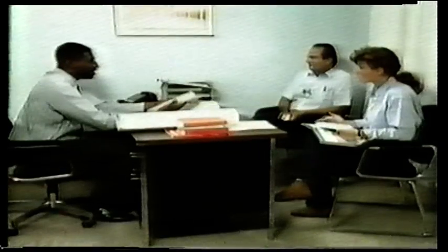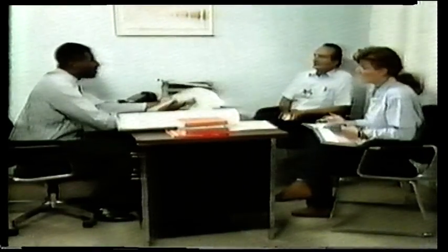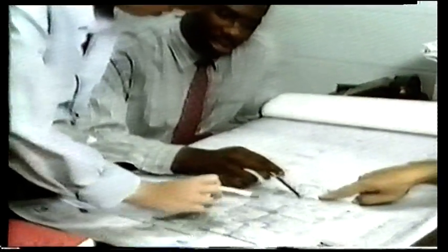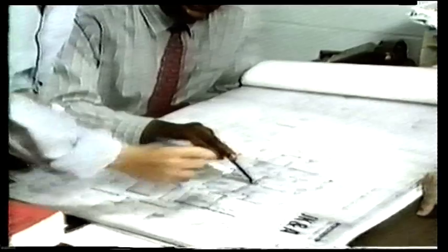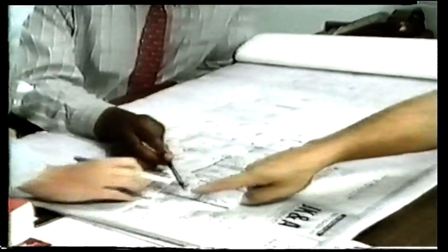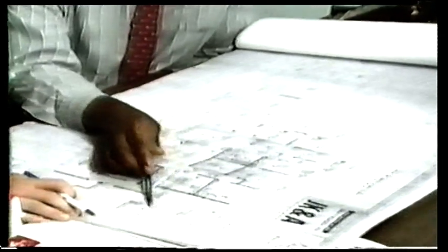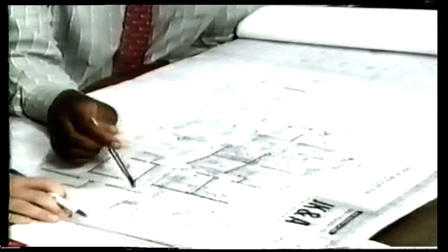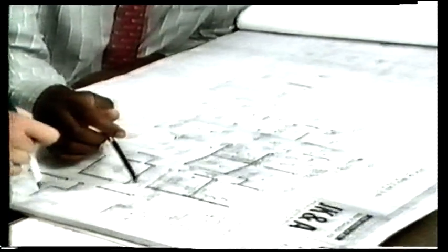The survey team should ask questions relating to the operation of the facility and how the public water supply is utilized. The answers will guide the survey team through the facility and the survey process, assisting them in noting key areas to be inspected. The survey team should request drawings depicting the facility's plumbing system. In older buildings, problems arise with as-built drawings because it is difficult to determine if they have been kept up to date. In new installations, as-built drawings may have great value and will show the survey team the extent and detail of the potable water supply plumbing system and how it is used.